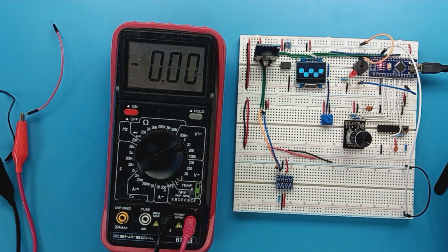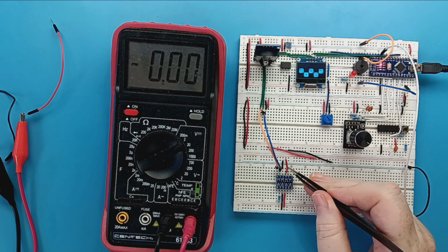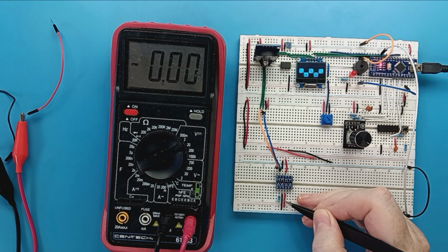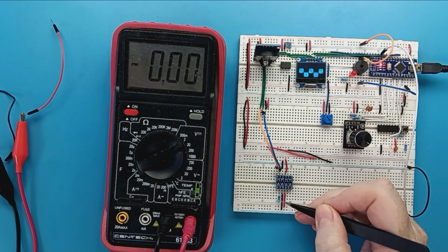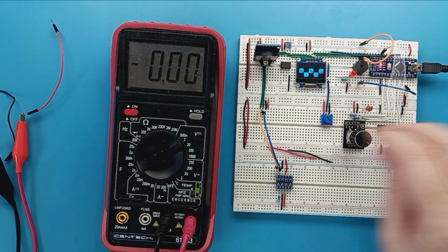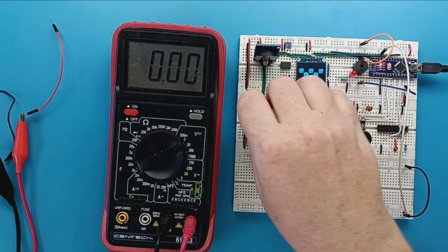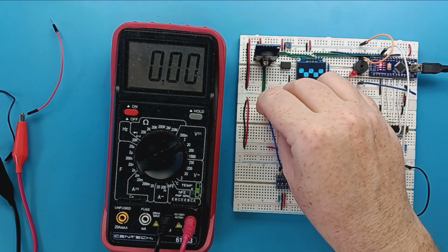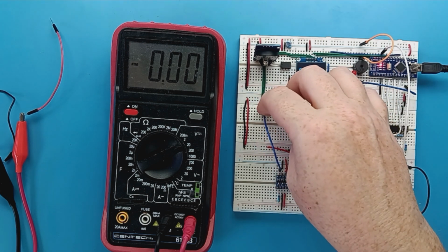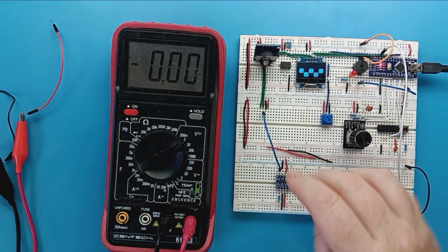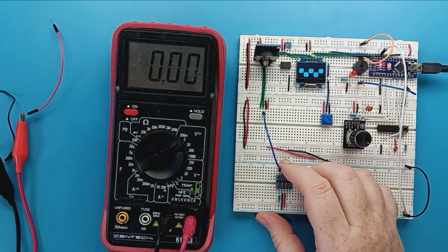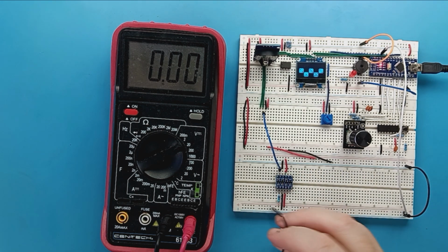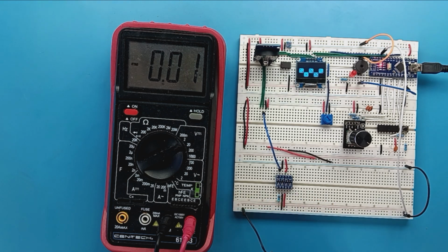So what I have here is both the 3.3 and the ground side connected up to 3.3. On the 5 volt side, I've got 5 volts and the ground on the 5 volts, and the pull-up resistor to 5 volts. I'll just use one because I've only got one resistor. So I'm going to take the clock line, and use this blue cable to bring the 3.3 volt clock signal across to this side. We're going to take a look at it on the scope, but just to confirm the voltages, I'm going to double check.